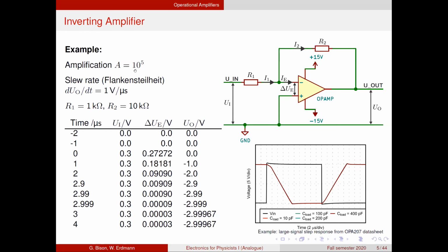Of course, it cannot do that. The supply voltage of the op-amp is simply plus minus 15 volts, and it cannot exceed those voltages. But its output wants to go, and in fact, the negative input here is at a higher potential than the positive, so it wants to go to minus 27,000 volts. And so what it does is it takes a step in that direction with the largest speed it can master.